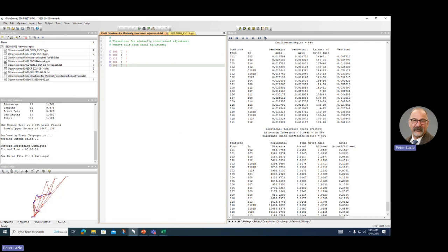It's two azimuth pairs, and I was going to use the spec says you have to have the survey manual, the standards and procedures manual for the survey for NISA says that the company has to have 4 GPS receivers. You have to possess 4 GPS receivers. How they come up with that, I don't know. But when you do your survey, you have to use at least 2. And because of our workload, I only wanted to use 3.